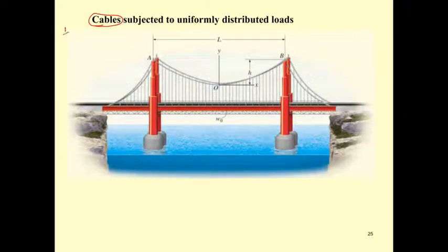And talking about the cable, there are some important assumptions that we are supposed to make. First, the cable is flexible, okay, and it can be any shape. However, it is inextensible. That means the cable will be subjected mostly to tension force. It acts like a two-force member, and the shape of the cable won't change much, or changes very negligibly, under the force.